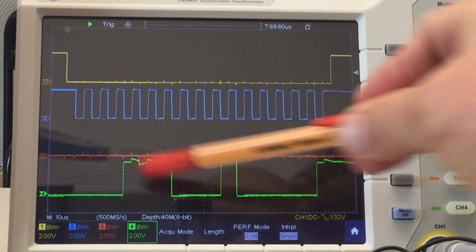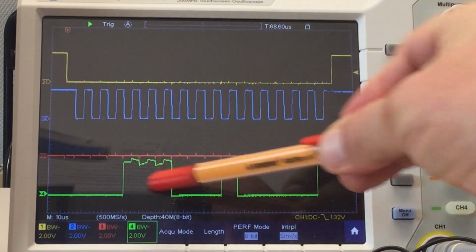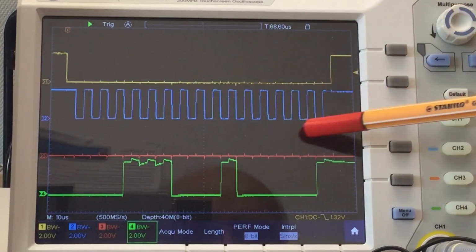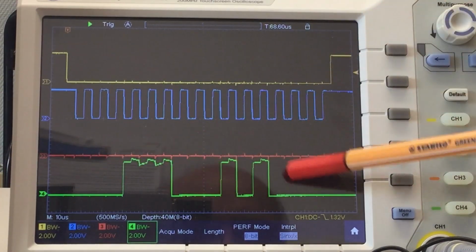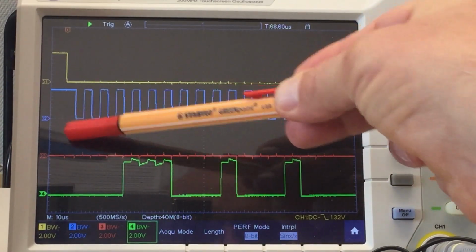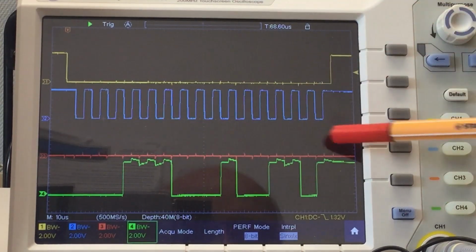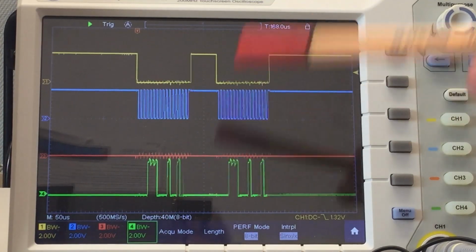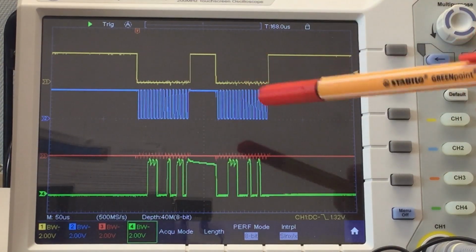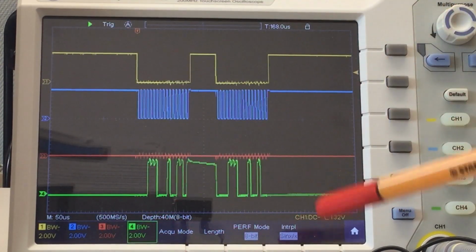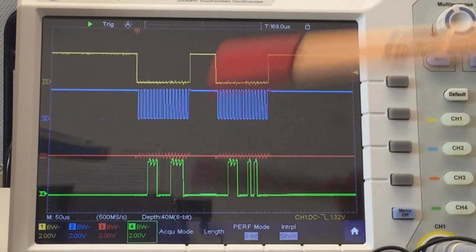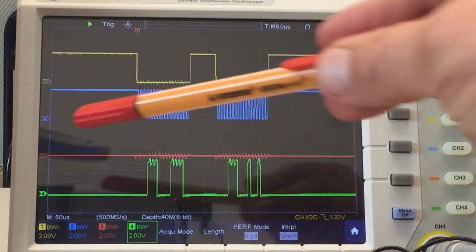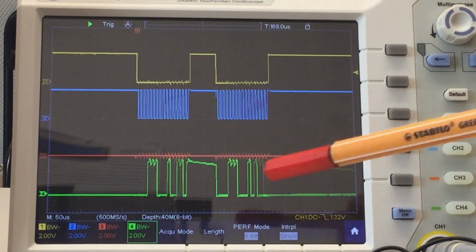But remember, the data returned here is not the data for that command here, but the data returned from the chip for the previous command, from the previous SPI transaction it received. So my whole read register function looks on the SPI bus like that. Remember, we don't cache or memorize what was the last command.